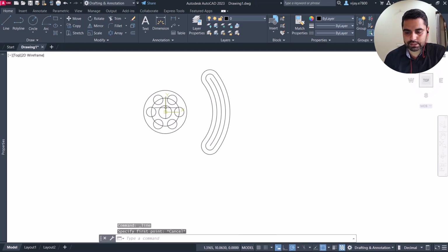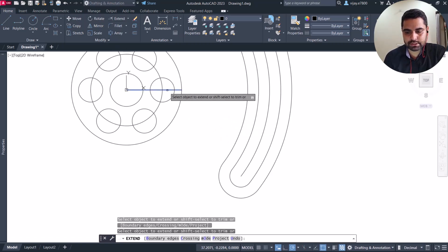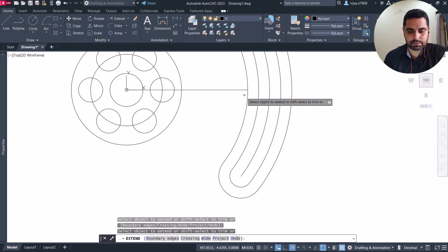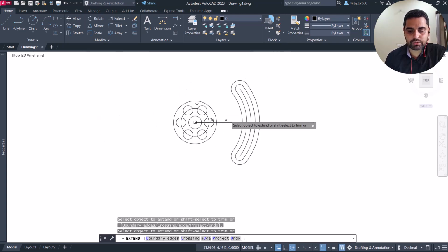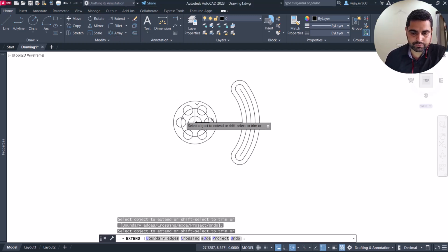Basically we need to extend this particular line. So click on extend alongside trim, then extend this line to the next possible boundary, and we are again going to create offsets for this particular line. Okay, so we will create offsets of 20 units.